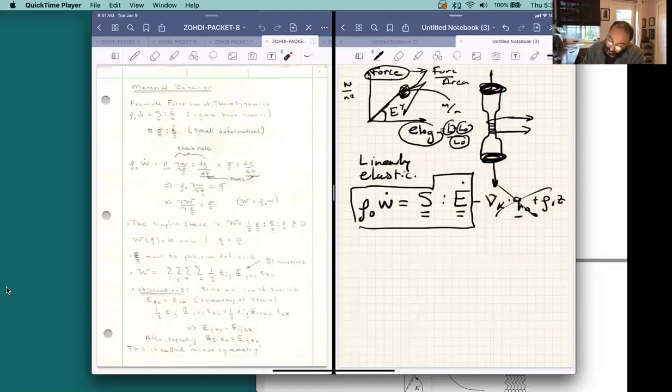So if we concentrate on the mechanical part first, when the strains are super small, meaning we're right when the material is about to deform, right here at the super infinitesimal scale, we realize a couple of things occur. Number one, the second Piola-Kirchhoff stress is equal to the Cauchy stress because we know that they're equivalent at very, very small deformations. So in fact, we can rewrite this as sigma, the actual stress.